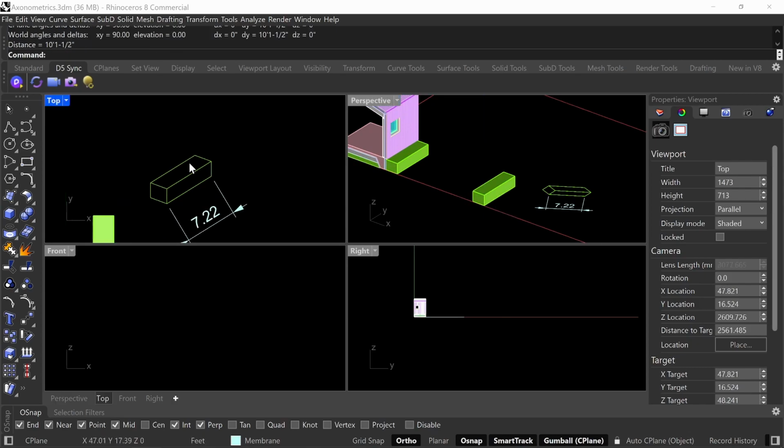You see, because when you do an isometric, it's a foreshortened projection of the object, but there are drawings that show the true length. And personally, I find them super helpful when you're doing very detailed drawings that you want to show three-dimensionally and show the true length of the measurements. It's very helpful in product design or in furniture design, where you're showing an actual object and you want to give them a three-dimensional view of it.